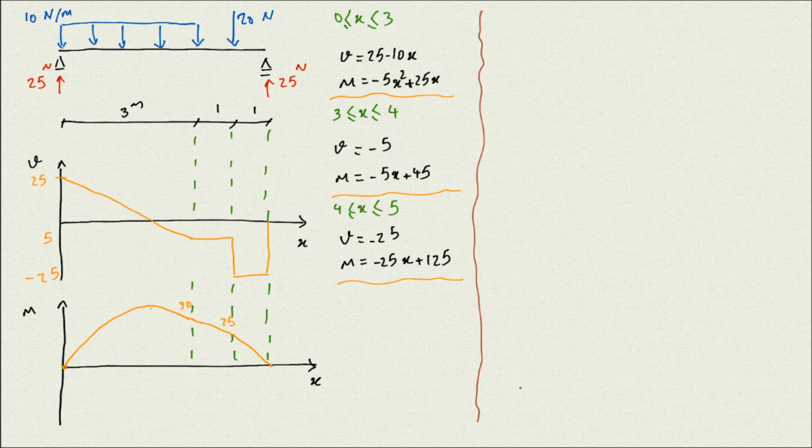If you look at the very start and end of the beam, both of them go to 0. So it's 0 here, and it's also 0 here. The whole point is that if we have a pin or roller, they are not going to withstand the moment, and they are at the end of the beam. That's the important point. They should be at the end of it.